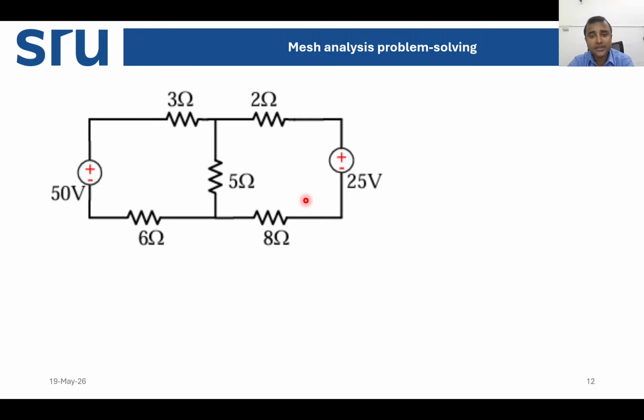Frankly speaking, Thevenin's theorem and Norton's theorem deal with the case where there is a particular load resistance and you don't know what is inside. Then by applying Thevenin's theorem you can transform the entire circuit into one particular voltage source and only one resistance.